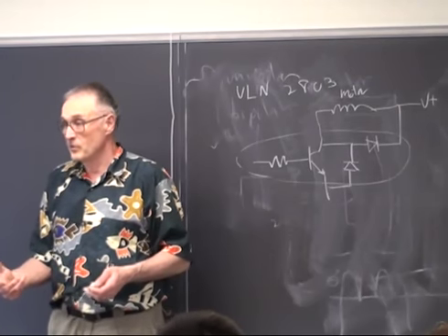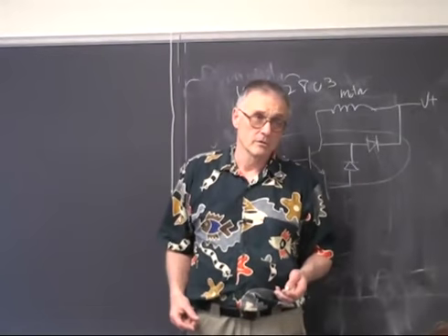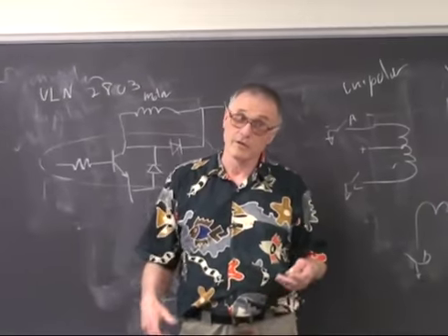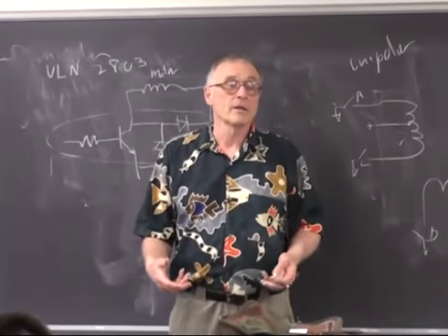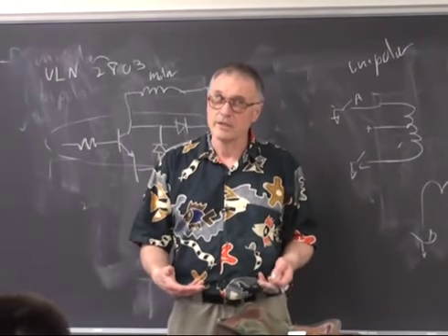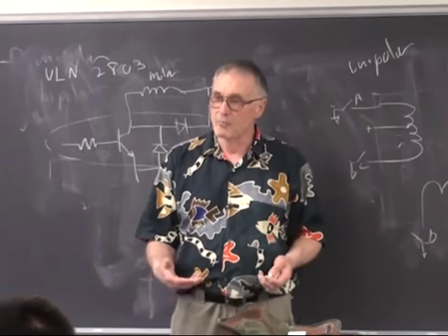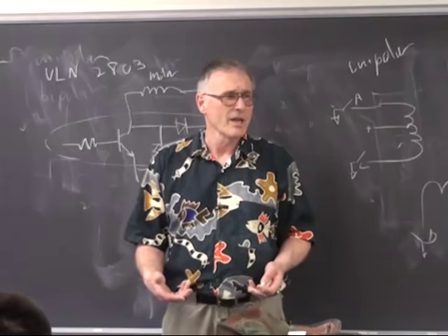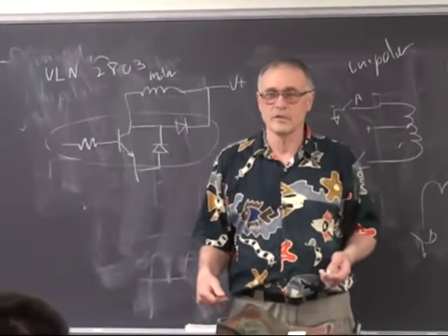If you're using bipolar motors, you have to use a decoded H-bridge. If you decide to build your own H-bridge with the level shifters and everything, then you will have to build the hardware TTL logic necessary to decode them, so you cannot possibly turn on the wrong set of transistors at the correct time. And I have some stuff online on how to design that. It's, I think, two TTL packages.